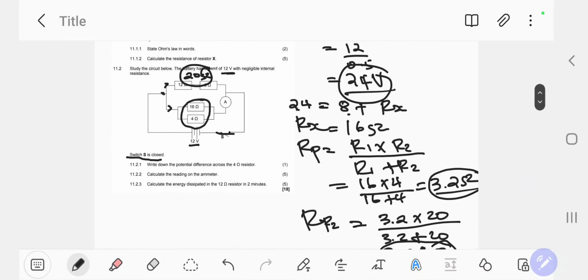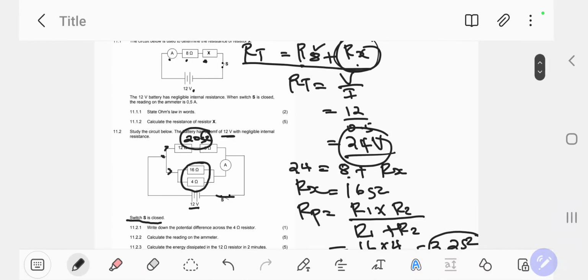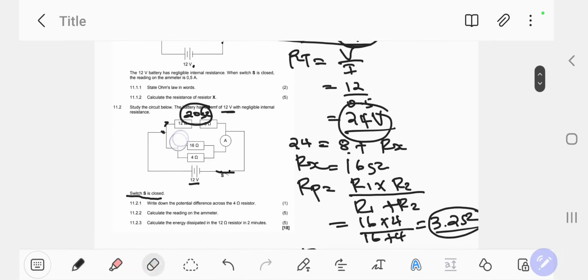Why am I saying that? Because remember, guys, for us to be able to get there, what we did with the circuit, we analyzed the circuit and understood that when the current gets to this point, the current is going to flow to that side and flow to that side. So now this is basically connected in series. We can add them. So it's going to be 20 ohms.